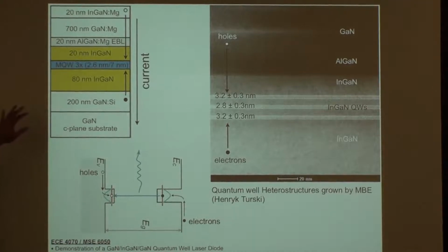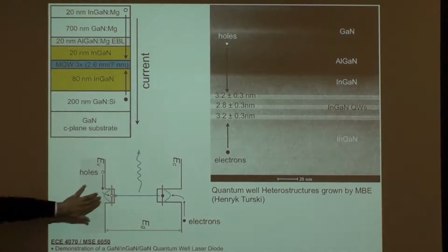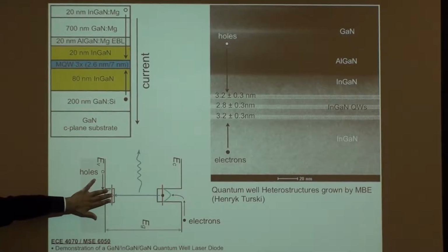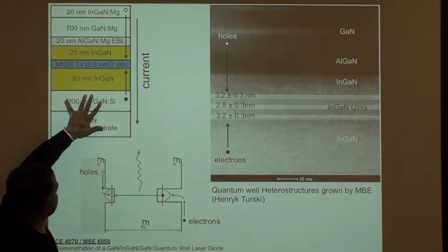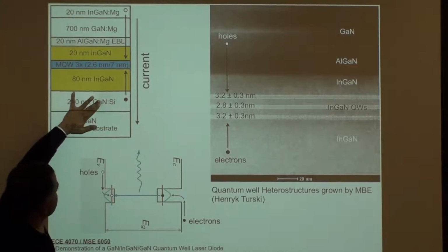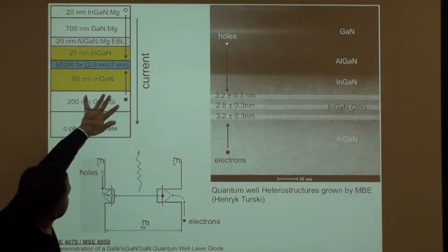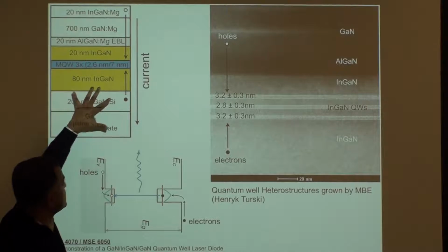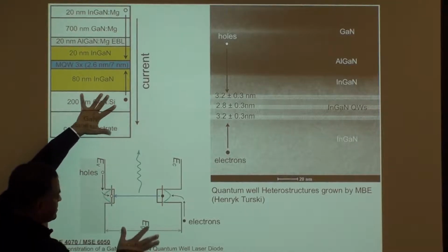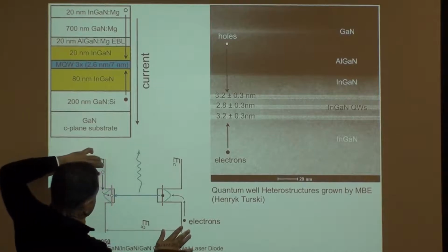It's acceptors. Right? And we've talked about, when you have acceptor doping, you're going to empty out some valence band states and make holes. You create holes there. And here you have doped gallium nitride with silicon. Silicon replaces gallium. It has one extra electron in the outermost shell. So it is n-type. It has electrons in the conduction band, but no holes in the valence band. So here's your n-type. And you have electrons in the conduction band. On the top is holes in the valence band.